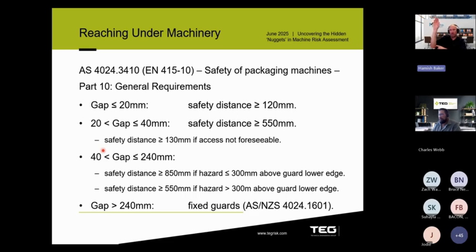They've applied a basis of risk to it, and they've set that 550 millimeters based on that. Now, I don't have a 550 millimeter long forearm to fingertip. I'd probably be in the NBA if I did, but that's where that number comes from. And it's just another way that you can infer there's a risk-based approach, based on some anthropometric reach distances that maybe you could apply into your risk assessment if you don't have clear answers for your particular use case.